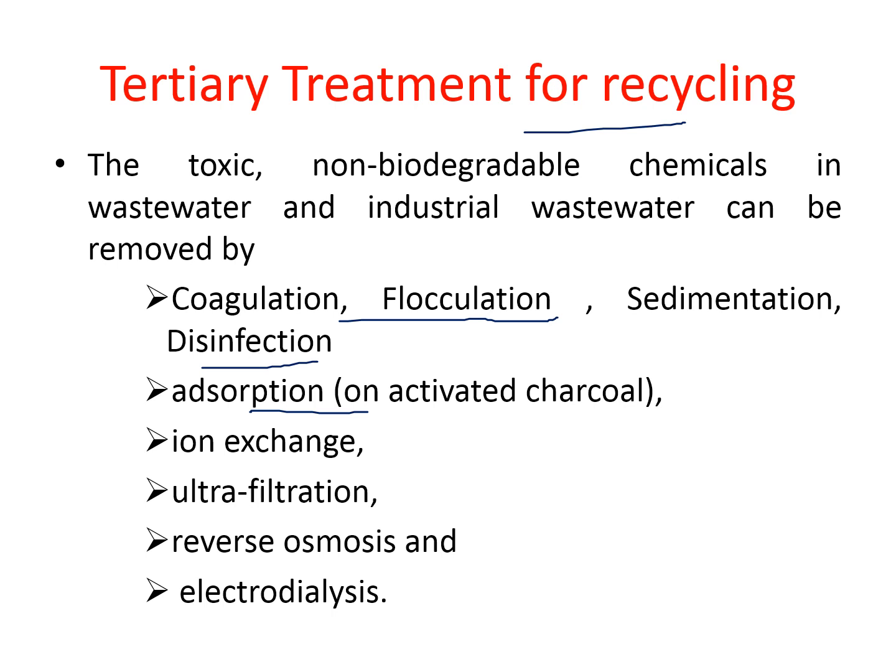So a filtration bed of activated carbon can be used, ion exchange process, ultrafiltration process, reverse osmosis process, electrodialysis process. So these are all advanced treatment methods. If you want to reuse and recycle wastewater after conventional treatment, then you have to go for this tertiary treatment method.